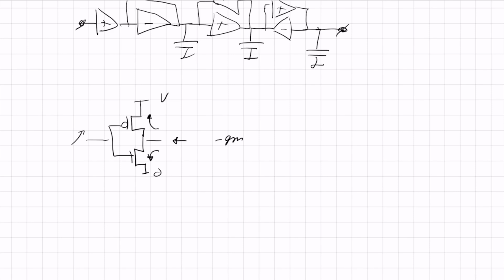And positive and negative, well, many circuits are differential, so everywhere where there's a positive signal, you also have an anti-phase signal, and then you can just take wires from the other side, and then you have opposite signals. So if you want a positive GM, you take the signal from the other side. And you have to take care of your common mode stability. There are some issues, but basically an inverter can already be a GM block. So it can be very, very elementary.